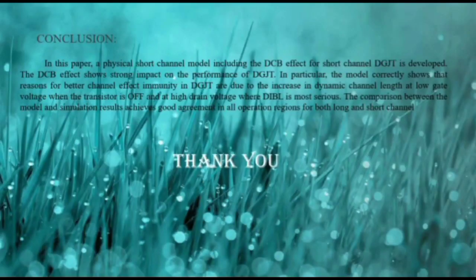In conclusion, in this paper, we have seen three important things. We have observed that at low gate voltage, the dynamic channel length increases in the double gate junctionless transistor and impacts drain induced barrier lowering. From the comparison between the model and simulation results, we achieved good agreement in all operation regions for both long and short channel. Thank you for watching our video.